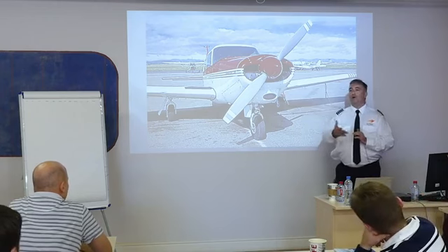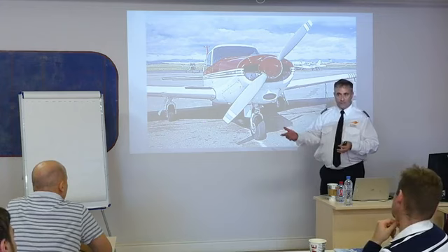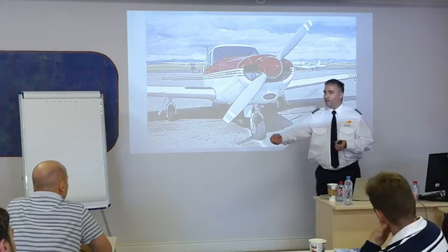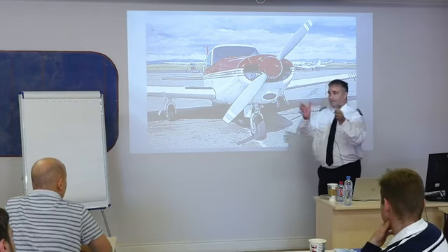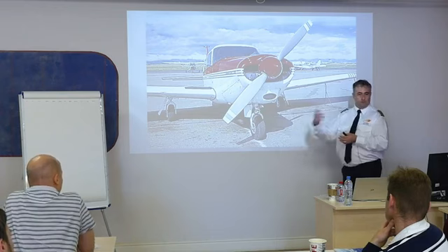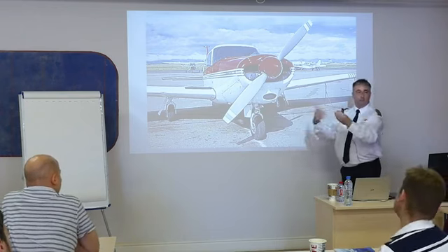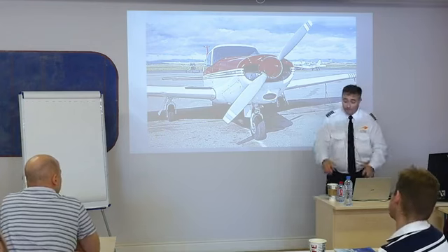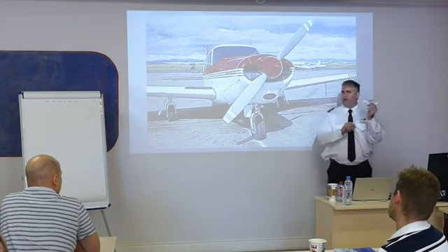So, if I'm going to make a before takeoff checklist, which I do every time, and I advance my throttle and check the engine and make sure it works, point that airplane into the wind so I get the maximum amount of airflow. Right? We're on the ground, we're at a moderate power setting, point it into the wind, allow maximum airflow. If I'm taking off and climbing, use a cruise climb.